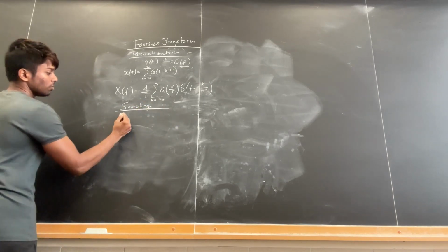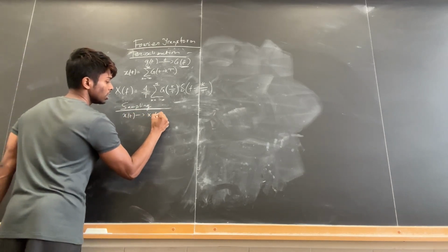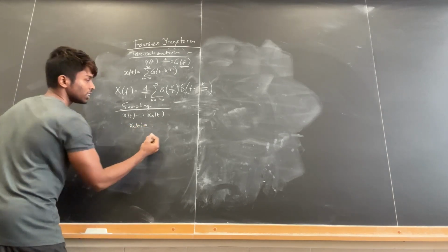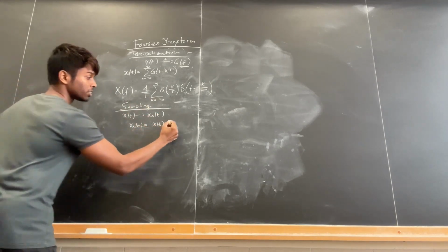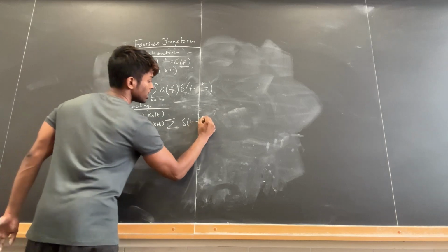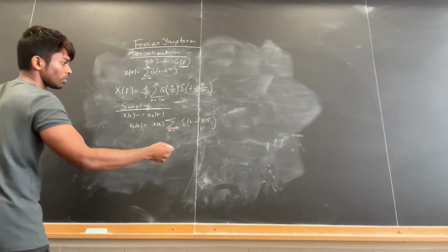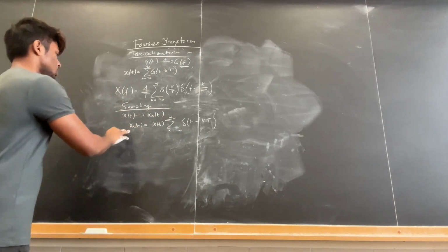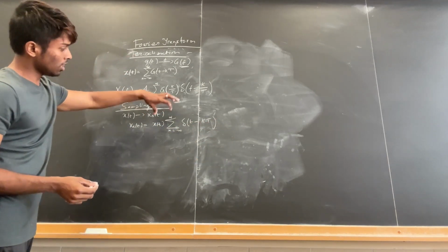So we have a time domain signal x(t) and we are sampling this signal to x_s(t). Now what is sampling? Sampling is basically multiplying the signal x(t) with an impulse train, which is a summation of delta(t minus kT), where k goes from minus infinity to plus infinity, or whatever interval we define. So x_s(t) is equal to this. This means we are multiplying the signal with an impulse train.